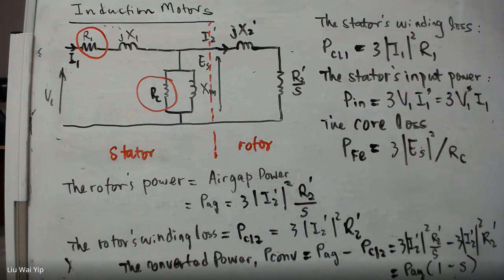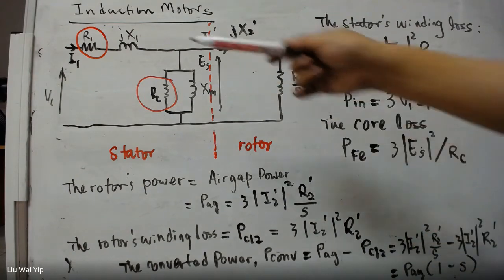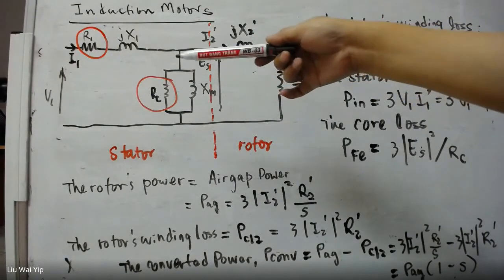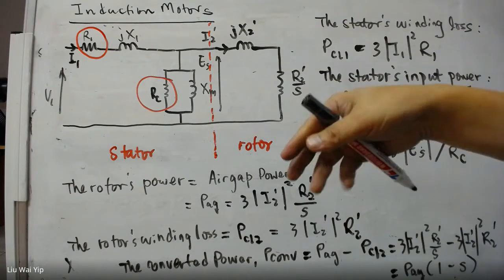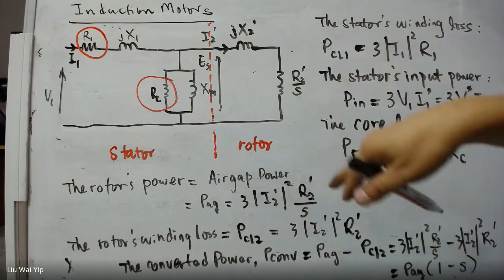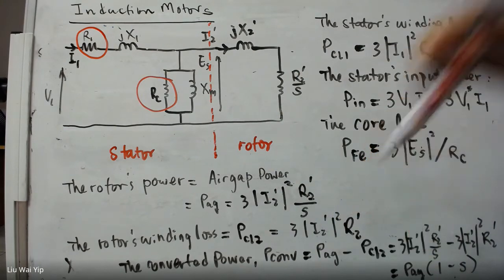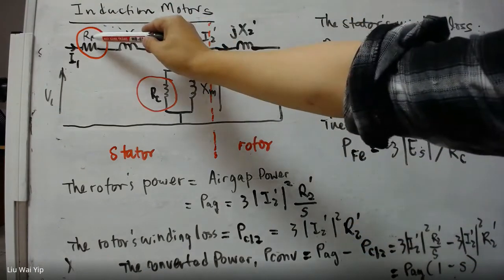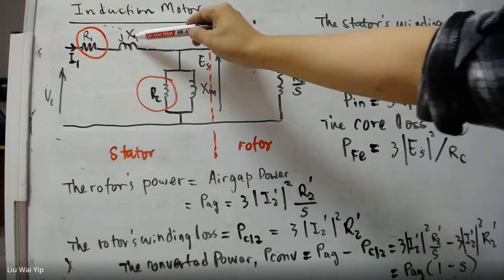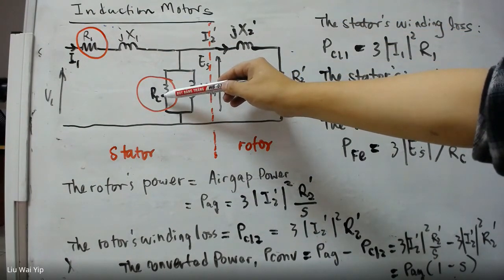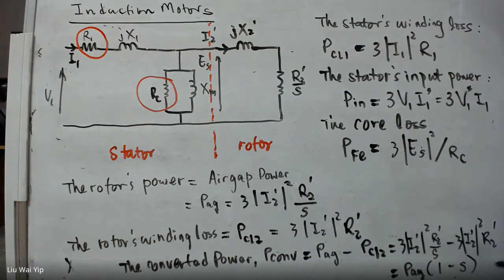rotor. And from here, we end up with the parasitic for the stator. And because the stator itself is basically a stationary device with an array of electromagnets, it's exactly the same as transformer with the winding nodes, winding impedance, and the core loss and the core impedance.